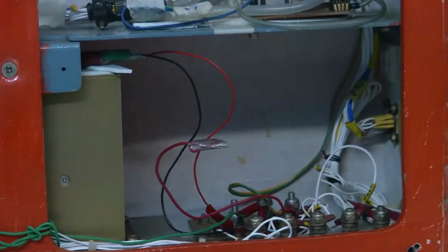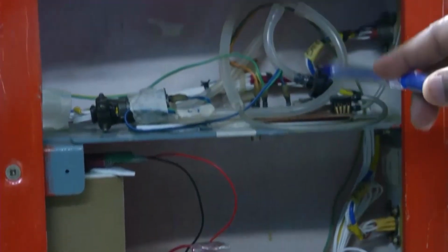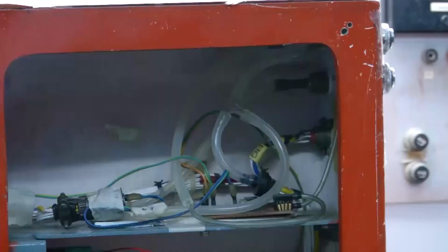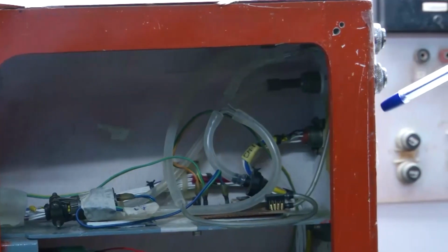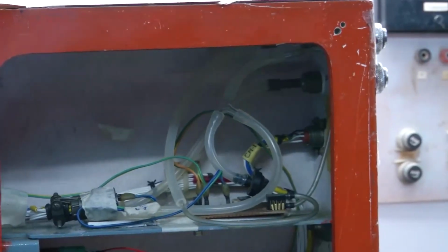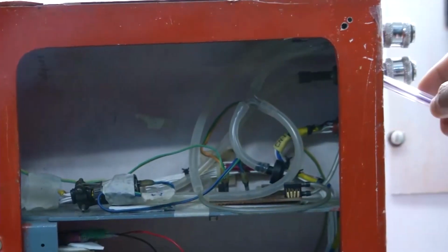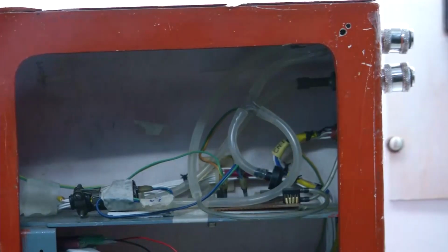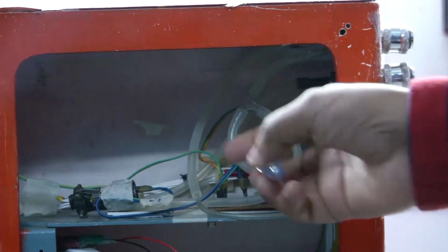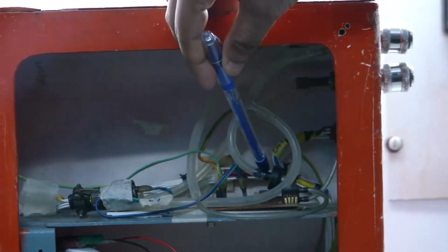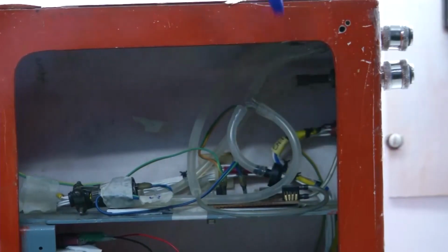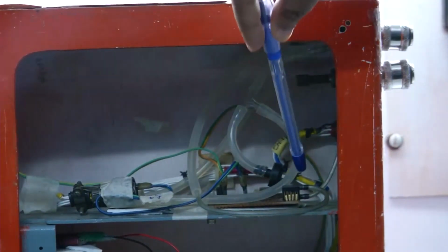And you can see there is a pressure sensor, and in this FDR there are two probes, 1 and 2. These correspond to your absolute pressure and differential pressure. Now these two probes will be connected to the probes of the aircraft, and corresponding to that you will be getting an absolute pressure and a differential pressure.